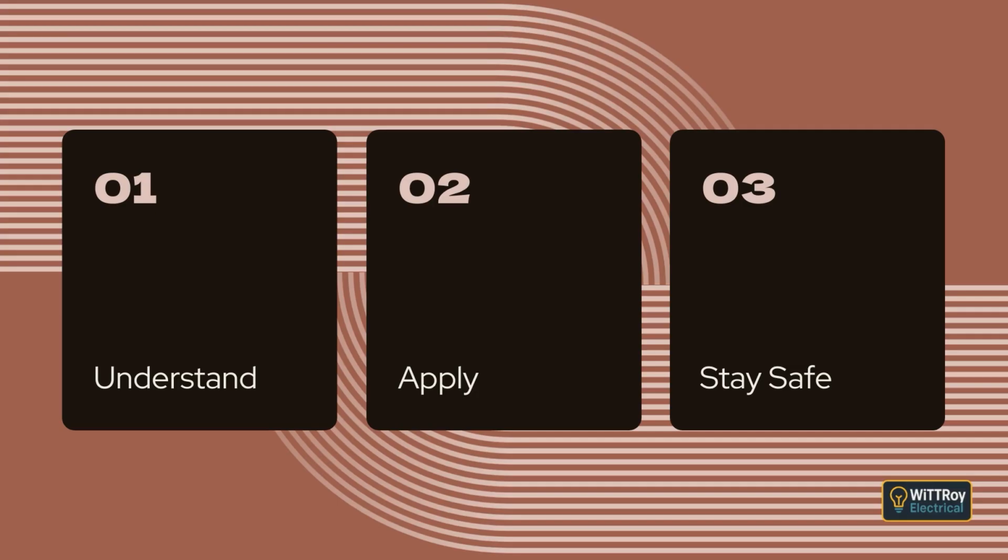Clause 3.7.2.9.2 Prohibited joints. Certain types of aerial cable must not be jointed at all while under tension. This includes parallel webbed or twisted aerial cables, neutral screened cables, multi-core aerial cables, and cables made from different metals. Clause 3.7.2.10 Underground cables. Joints in underground wiring must be sealed to prevent water entry. Proper sealing ensures long-term reliability and prevents corrosion.